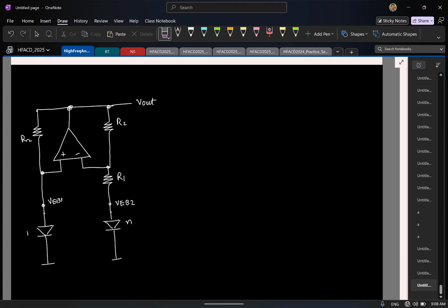Okay, so now tell me, I have this structure here. I have to sense two inputs, amplify and give a single-ended output. What kind of circuit can you use here? The 5T OTA you can use. And again, you want a very high gain, so you might want to put cascodes or something. So let's say this has a high gain.